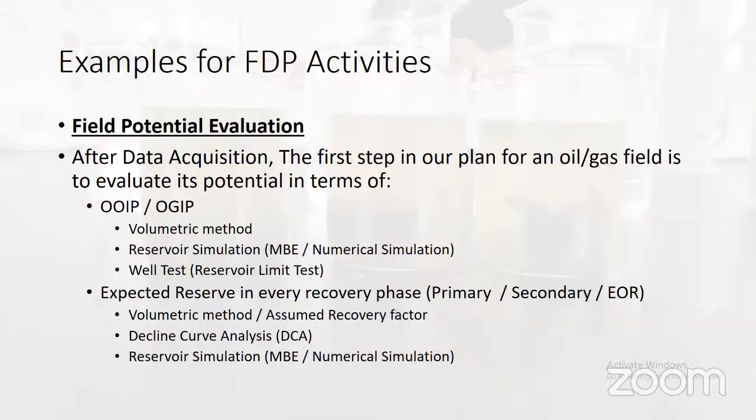If we have a field surrounded by other fields, we will ask the other companies what the drive mechanism in their reservoir is. If they say depletion, we will assume we also have a depletion drive mechanism in our reservoir, so we will use the recovery factor for depletion drive. That is the case when we use the volumetric method with only an assumed recovery factor.